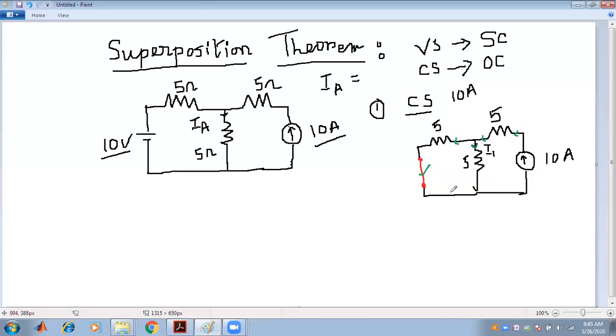And it is routed back through that part, and at that point two currents are coming, and the 10 ampere is also coming back in this way. Means these two are connected in parallel because the current is divided. One is I1 and the other is 10 minus I1. Current is divided, which means those two are connected in parallel. So in order to find the value of I1,